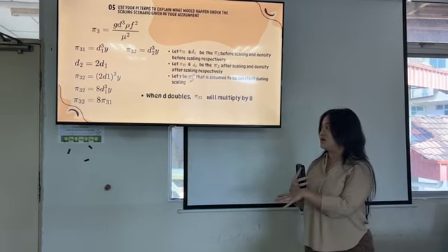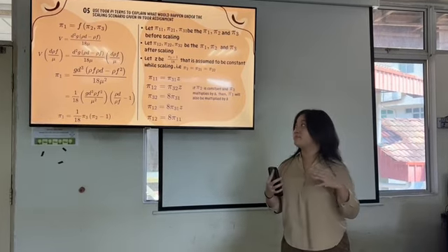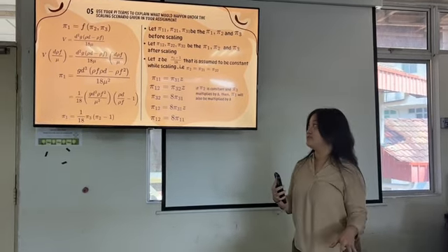Okay, so we've tackled pi 2 and pi 3, so now I'm going to tackle pi 1. So we know that pi 1 is a function of pi 2 and pi 3. And from our governing equation, we can basically replace some of the terms using pi 1, pi 2, and pi 3. So basically we represent some of the terms in the governing equation with our pi values. And after replacing it, we simplify it to pi 1 equals 1 over 18 pi 3 multiplied by (pi 2 minus 1).